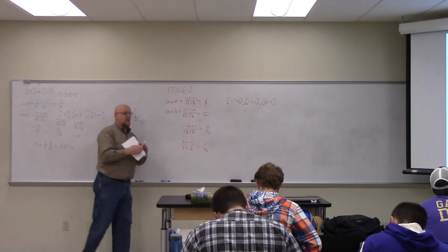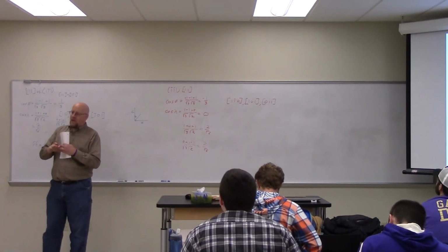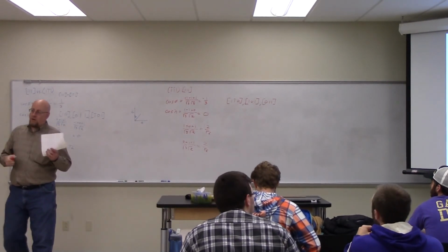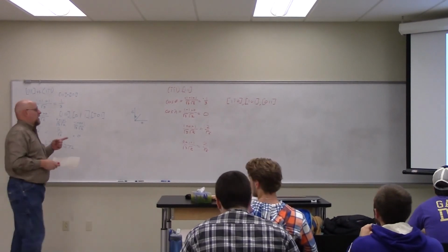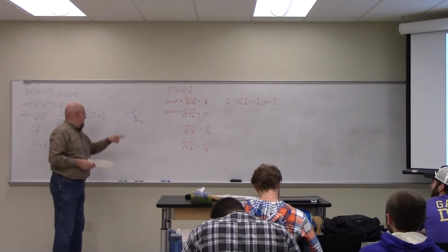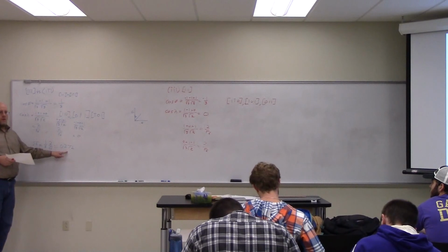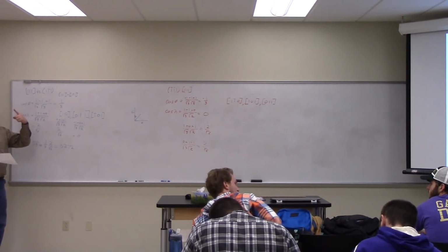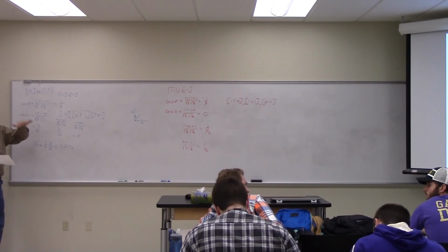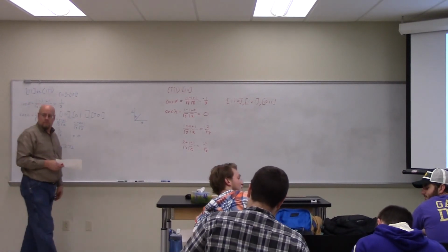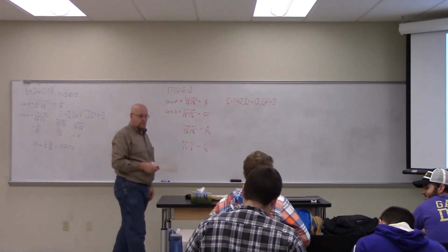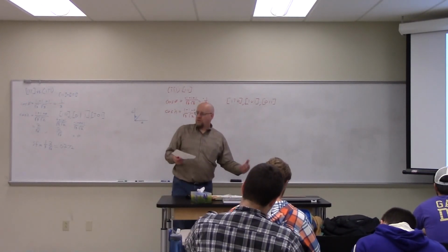So it turns out the red one and the yellow one, and in fact the green one, all three have the same Schmid factor of 0.272. So all three of those are equally active as compared with the one on the bottom. So is it just random then which ones can slip? So then, yeah, any of those could slip.